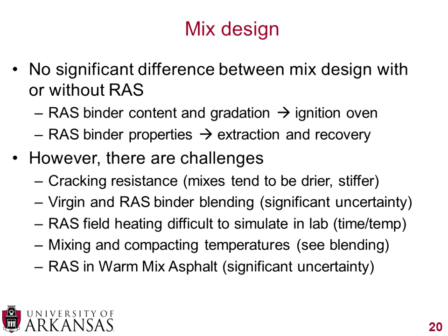Now there is an AASHTO standard, and I'll type it into the chat box here. AASHTO, let's see, PP 53-09. So AASHTO PP 53-09 is design considerations when using reclaimed asphalt shingles in new hot mix asphalt. So there is some guidance here. Unfortunately, I didn't go over this document before the webinar because I didn't recall that it existed. But I encourage you, it does have some tips in there about design considerations when using RAS.